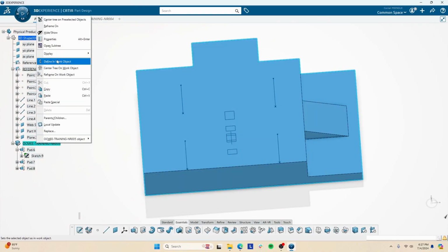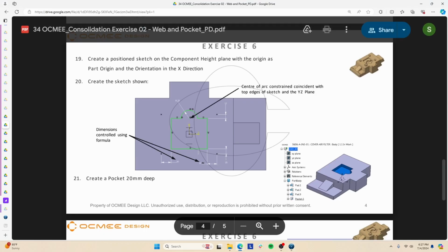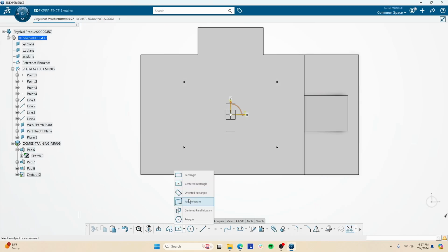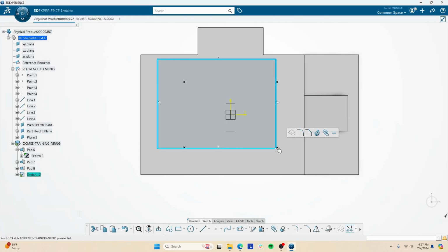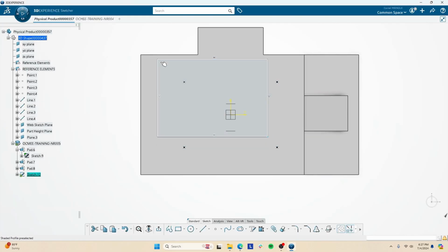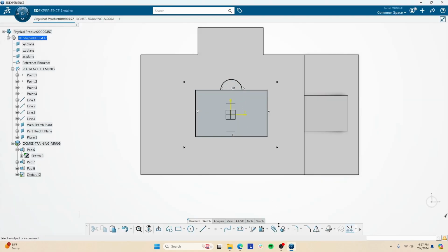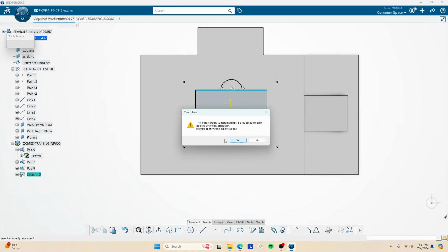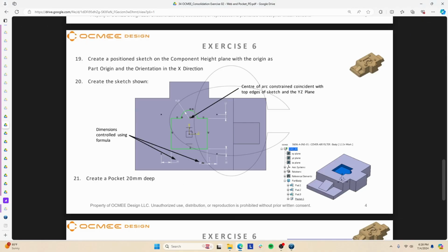So we'll go back to our main body. You see how that's underlined now? Create a sketch. And I'm going to just make a point-to-point rectangle. It seems to be smaller than the dots here. So I'll just roughly get it into position of a circle that bisects it. Seems like I trim off here and here. Yes, you can confirm this. It'll adjust accordingly. I'll put in my dimensions, 30 on that side, 30, 15, 12.